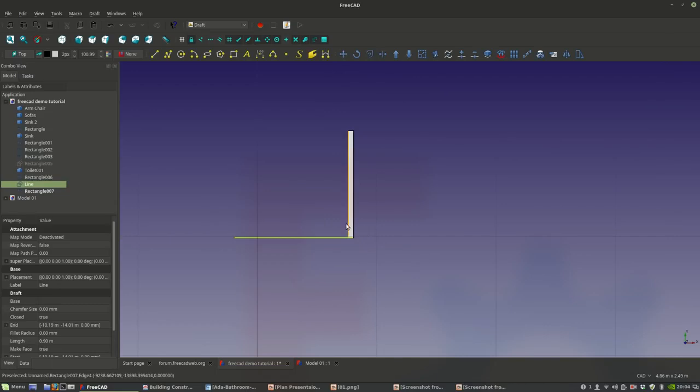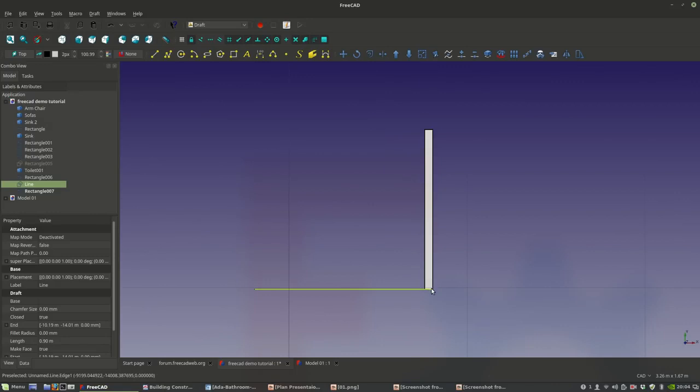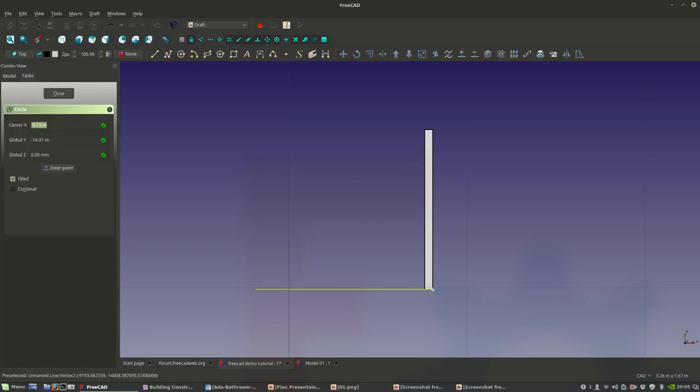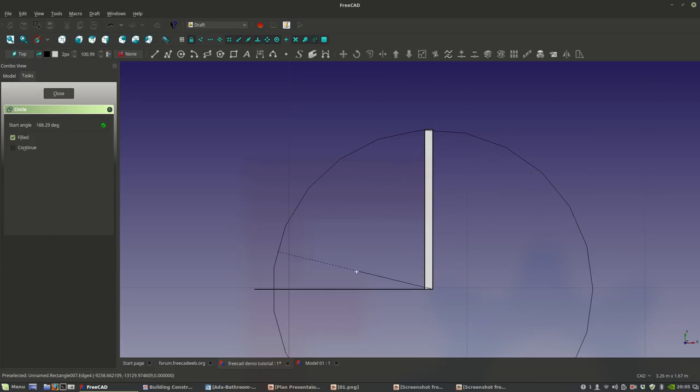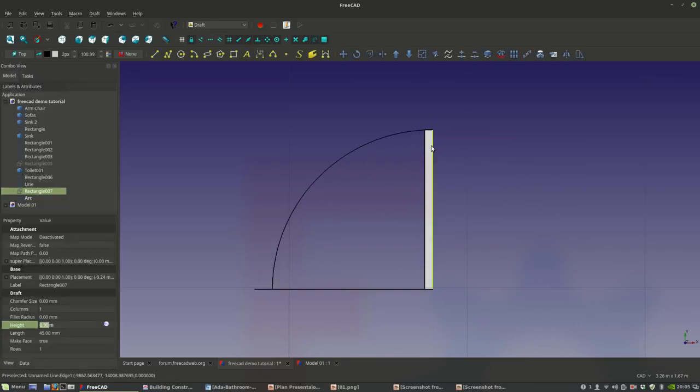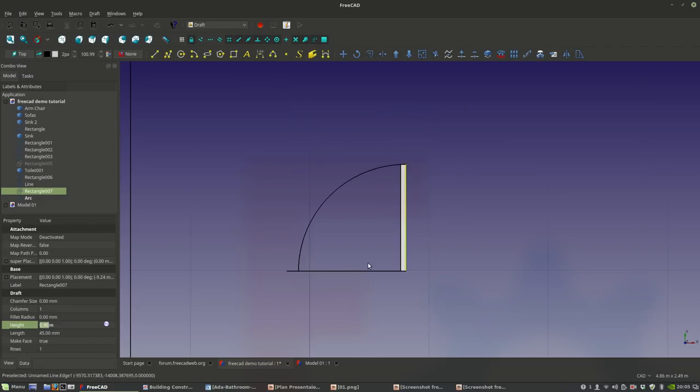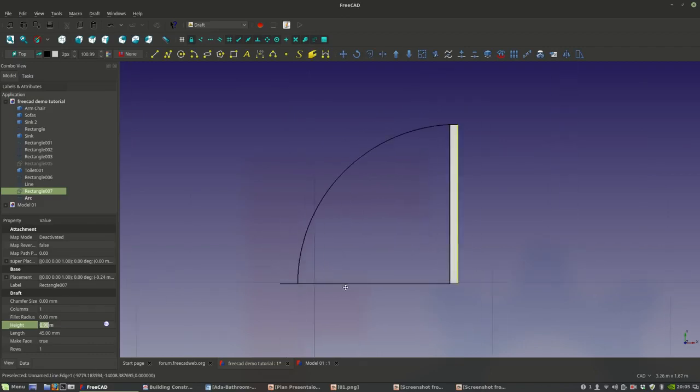And so how does the door swing go? The door swing goes from this edge to this edge, so it locks down like this. So I want to take the arc and start from right here and snap right here and snap right there and just draw a line like that. So that's my door. It's looking good.